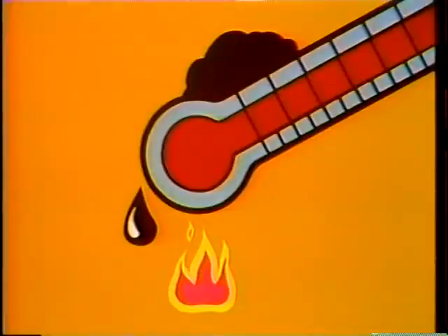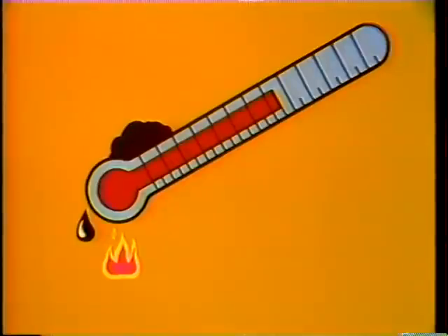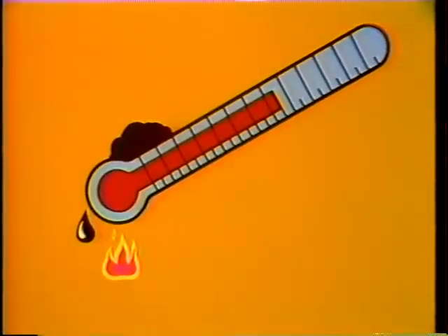The important properties of grease are its melting point and its consistency. The grease's melting point is called its drop point because of the method used to measure it. The grease is heated slowly until fluid begins to drop from it. The temperature at which the drops form is the drop point.